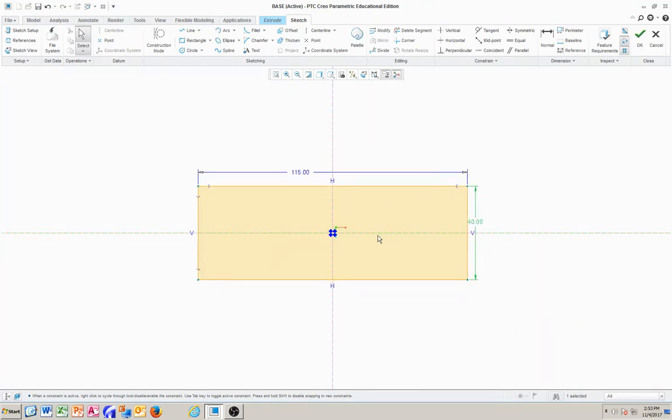Then we're going to create 4 holes in here. We're going to have 1 hole here, and then we go down, and this is another hole, equal radius, and then we go down again and say equal radius. Now we give the dimension here, from there to there, it should be 10. And this dimension here, I think this dimension is 10.